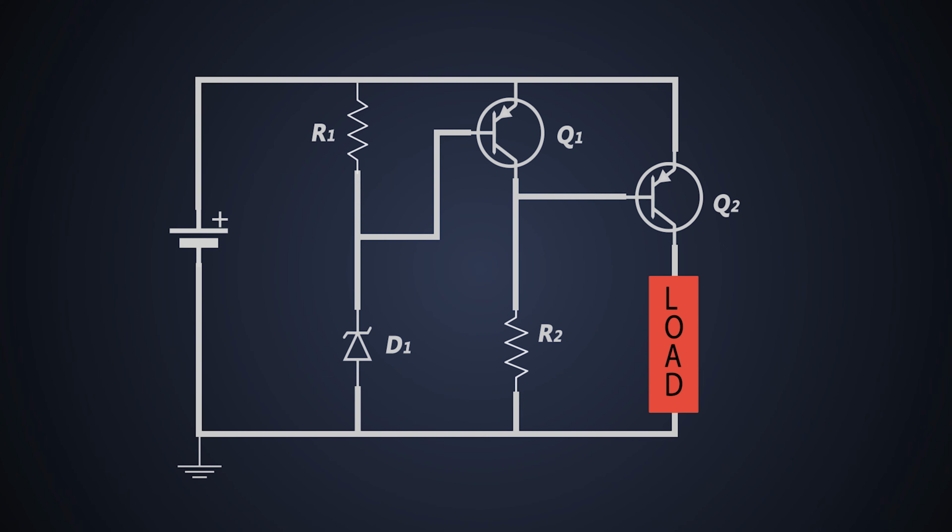Let's take an example that the input voltage is 13 volts and we are designing the circuit in such a way that when the voltage goes beyond 18 volts, the overvoltage will get activated and the circuit will be cut off by the transistor. Main requirement of the circuit is that the current handling capacity of the Q2 should be higher than the current flowing through the circuit.